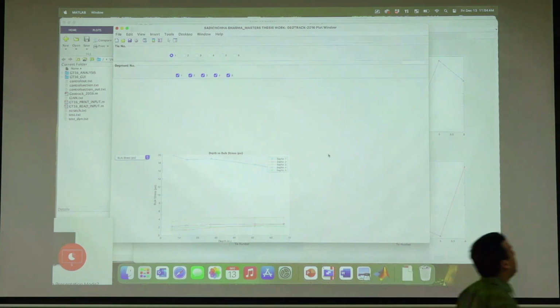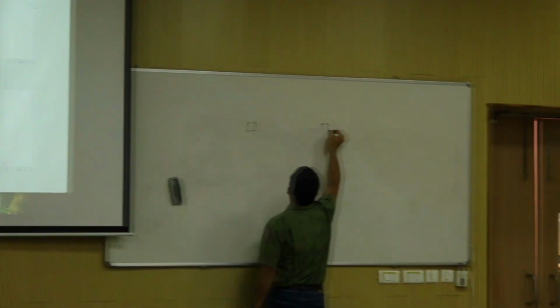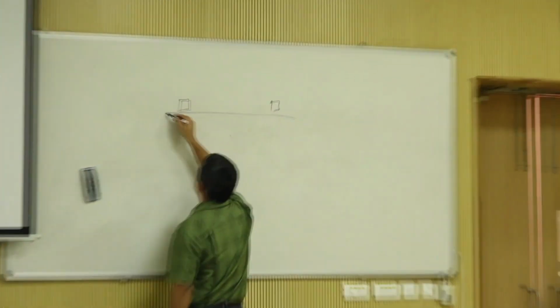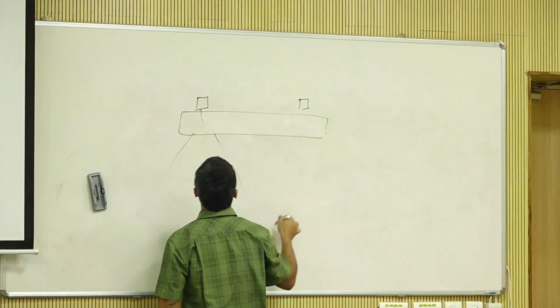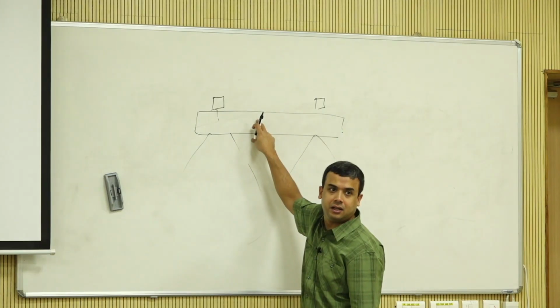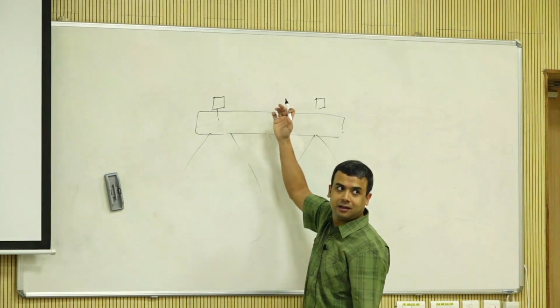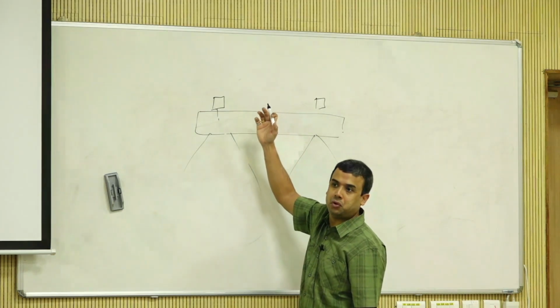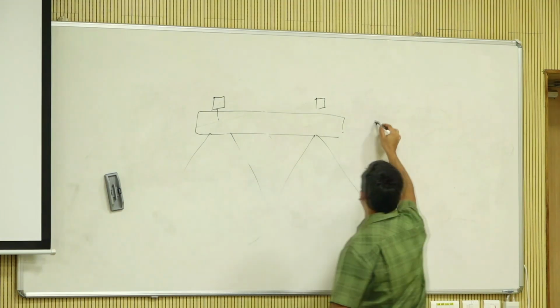If you look at the cross section, this is the rail, and there is a tie underneath here, right? So the loads are coming through this and then going like that and like that. So the question is, when you design a tie, do you really need the same thickness in the middle? You don't, right? Because there is nothing happening here. So that's the reason tie designs are usually like this.